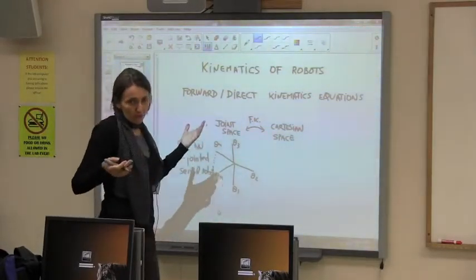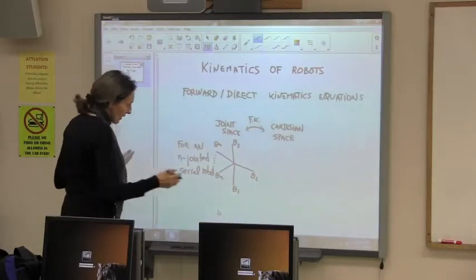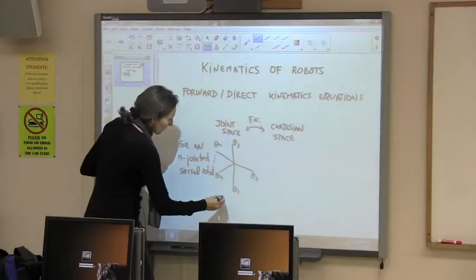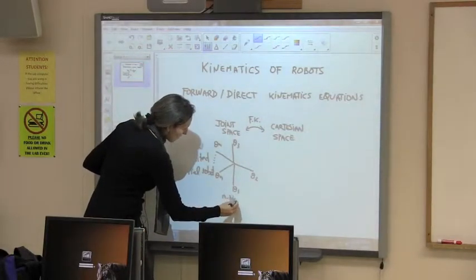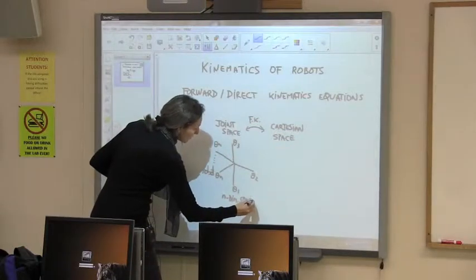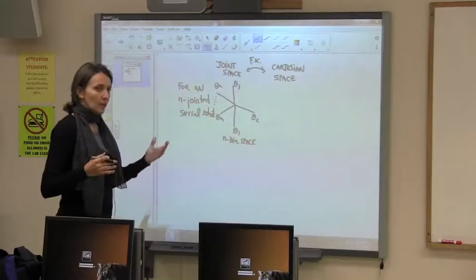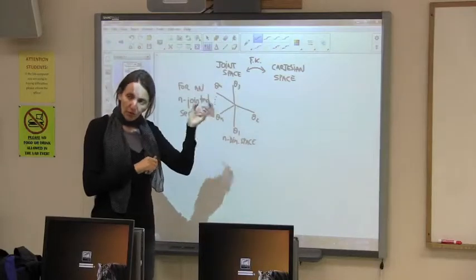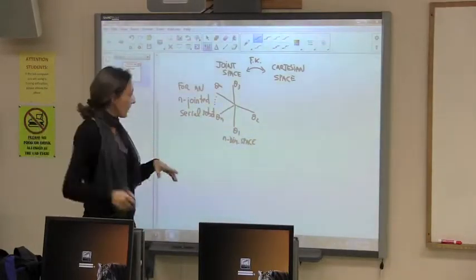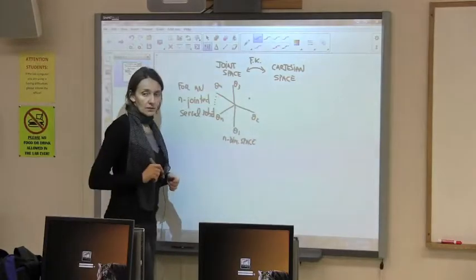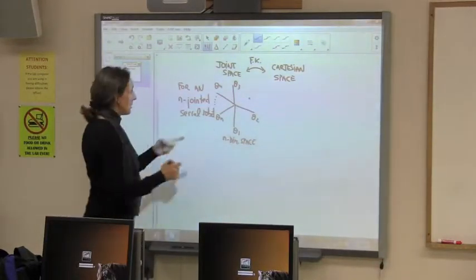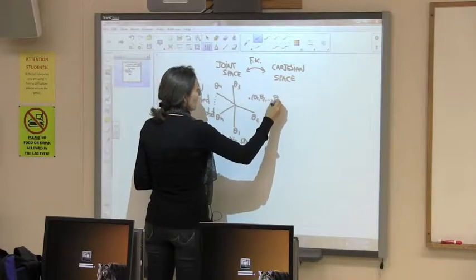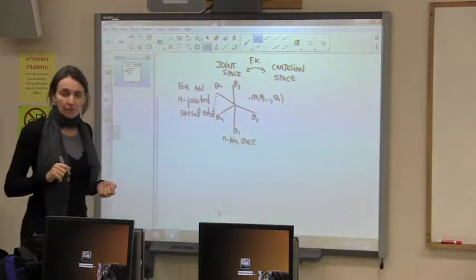The joint space is just an n-dimensional space, isomorphic to Rn, in principle without any complication if you don't impose any relation between the joints or limits or so on. It's kind of an abstract way of saying, when you move the first joint to theta 1 degrees, and the second joint to theta 2 degrees, and the third joint to theta 3, and so on, you are just defining one point here. One point is a set of values for your joints. So for instance, this point will be your theta 1, theta 2, theta n. That will be a point in your joint space.